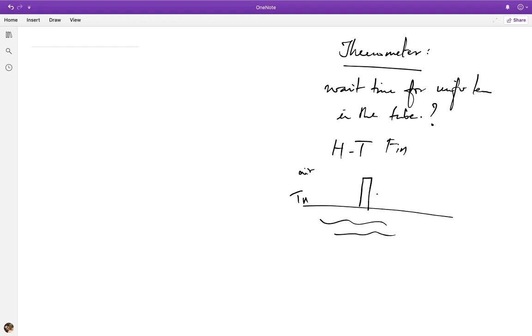Now typically we would be interested in modeling the temperature of this fin only in the z direction, where z is the upward direction, and if y is the cross fin direction, we typically neglect variations in y. And the argument usually is that y is so small, the distance in the depth of the fin is so small that the temperature T basically becomes uniform almost instantaneously by conduction.